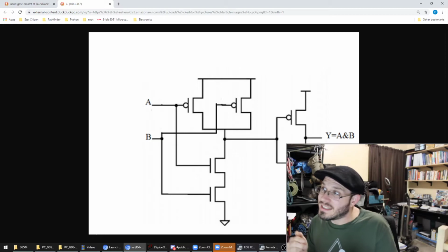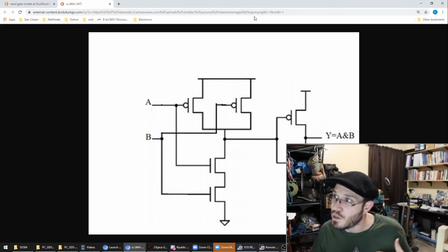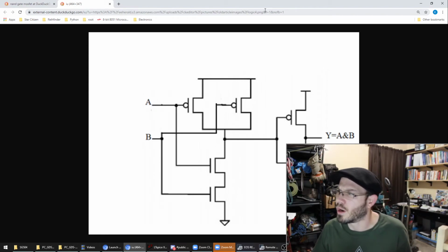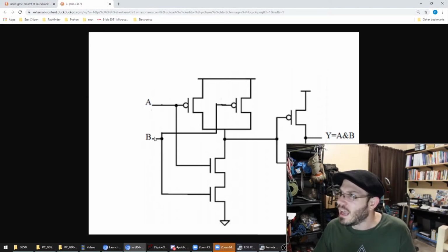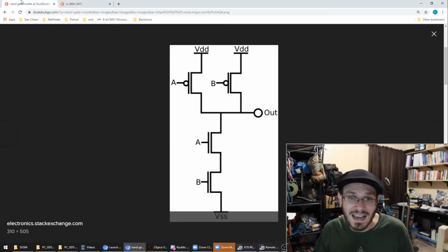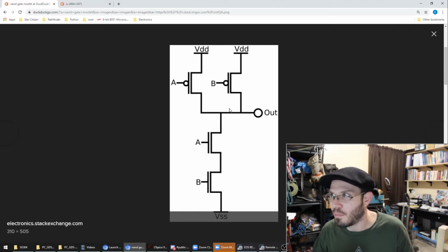So even though the symbol, when you're writing out your digital logic and your Boolean algebra, you probably mentally think that an AND gate and an OR gate are more intuitive and simpler because you don't have that extra negation. But from a hardware level, that's another 2 transistors that you need to put at the end, and you have to follow it up with an inverter. Whereas a NAND gate has no inverter stage afterwards. So a NAND gate is more fundamental from a hardware perspective.